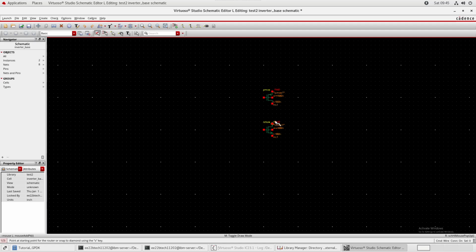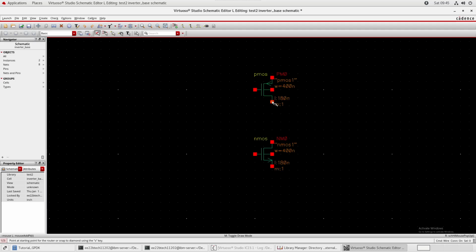Again, you can do wire by clicking on this create narrow wire, or by pressing W. This is again small w, and what you can do is click on this, it will make the wire. For undo, it's U, small u. Another thing you can do is, when you're in this mode to make wire, as you can see on the cursor, you can press S and it will select wherever this diamond is.